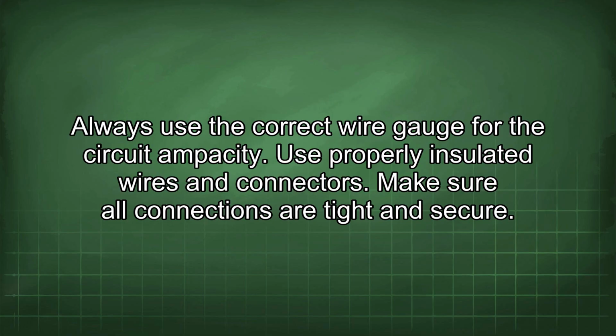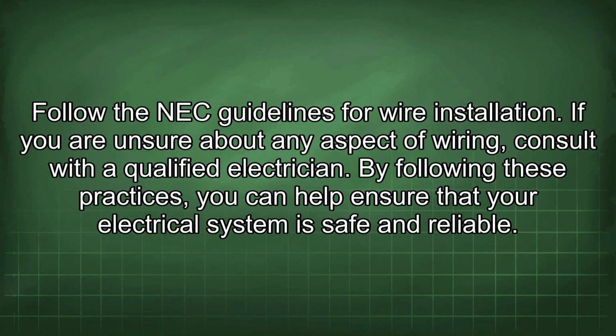Always use the correct wire gauge for the circuit ampacity. Use properly insulated wires and connectors. Make sure all connections are tight and secure. Follow the NEC guidelines for wire installation. If you are unsure about any aspect of wiring, consult with a qualified electrician. By following these practices, you can help ensure that your electrical system is safe and reliable.